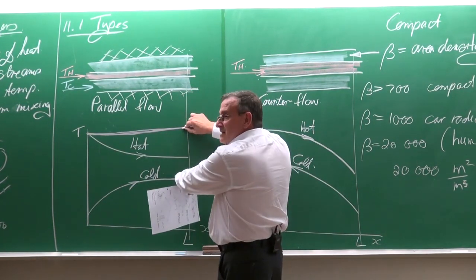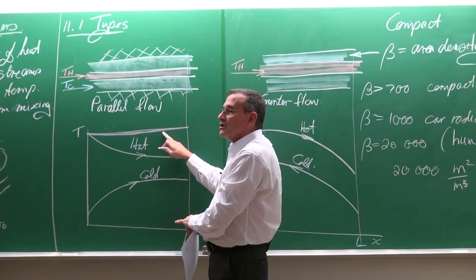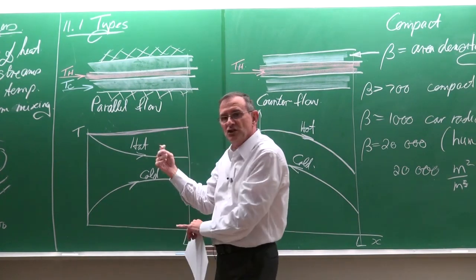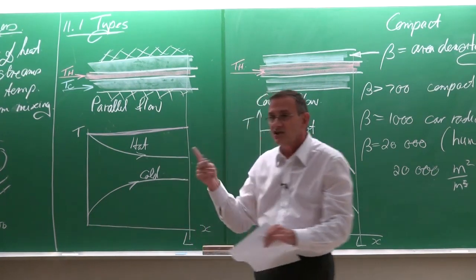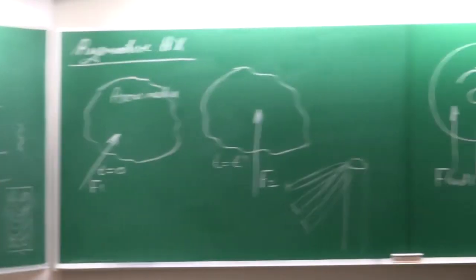And as you can see, the difference is obviously the heat transfer rate. So it will mean that the best types of heat exchangers, the most efficient types of heat exchangers would be heat exchangers where on the one side you have condensation, okay, or boiling or evaporation. So that would be for condensation.